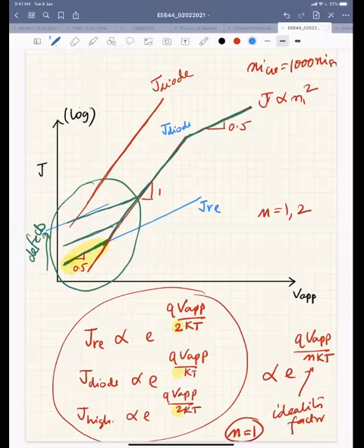So it is again, your current will be 10 to the 6 times lower. There also you'll see the recombination current. Your ideality factor will be even higher than in silicon, right? The ideality factor is a modeling concept, so as a device engineer, we don't really consider the ideality factor.